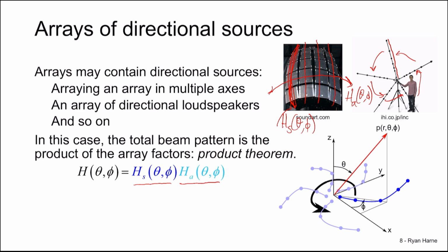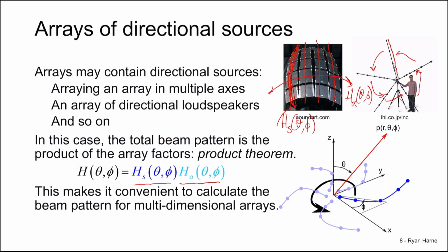This makes it very convenient to calculate the beam pattern for multidimensional arrays, especially rotationally symmetric arrays, for which it's not immediately apparent how to take all of the transducers at the outset and determine a total beam pattern.